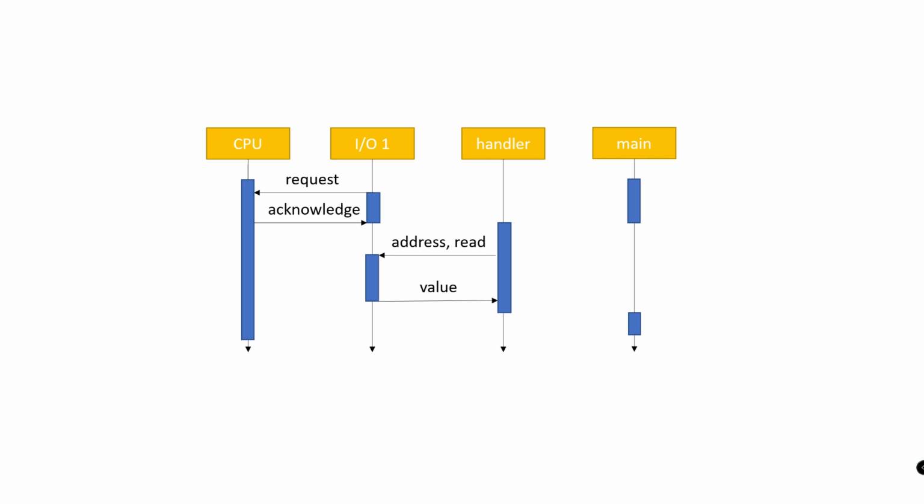In the CPU, a software function called a driver performs the read and write operations on the I/O device. The driver handles both the device registers and interrupts. Memory locations are assigned to I/O device registers. For example, a simple driver can be used to interact with an LED on the processor board.